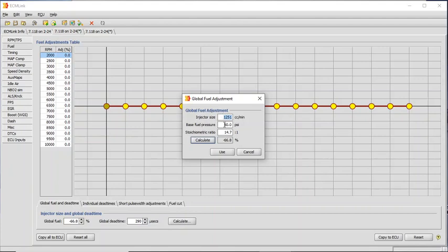When you get your base fuel pressure here matching what you're actually running, you may want to figure out what that is. That'd be helpful. If you're just on a stock fuel pressure regulator, then I'll try and post up a link as far as what those settings should be. And if this is a stock program to you, first time getting it out, whether it's a 1G or 2G, it may have those stock settings here anyway, so you can probably just leave that alone. And if you're on pump gas, you'd just be leaving this alone as well.